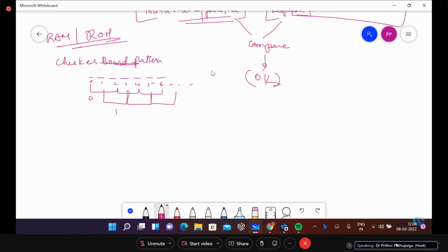This will be applied to the board, or the memory element, and the response of that applied input will be taken and again compared with the fault-free line. The next step is that after taking the even-odd as 0, 1, you interchange, making the even-odd 1, 0. This we call the checkerboard pattern of testing the RAM. Another test is that we have the March test also. March.